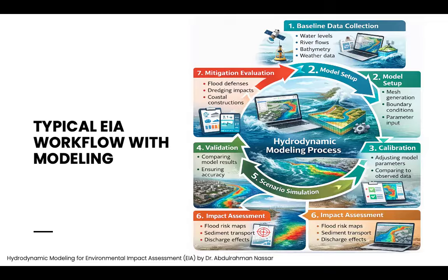For example, if we are talking about temperature dispersion or thermal dispersion, in a place like Egypt or the Middle East, we should consider the summer season and the winter season. So here we have two different scenarios at the beginning, and we could have more. To set up a model, first we make the scenarios, and then we set up our model by generating a mesh.